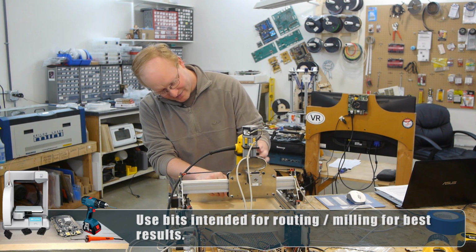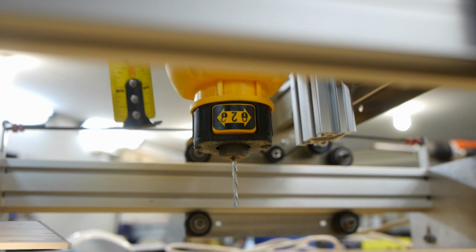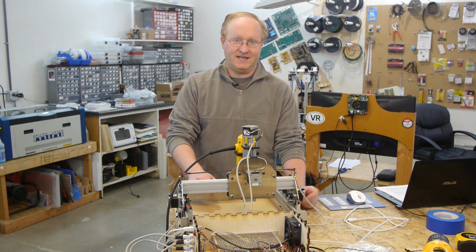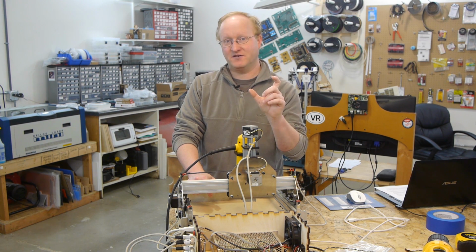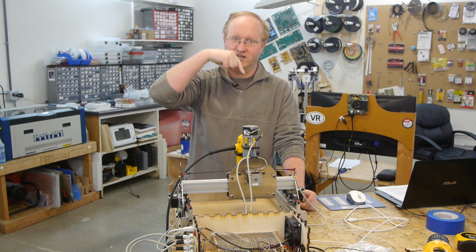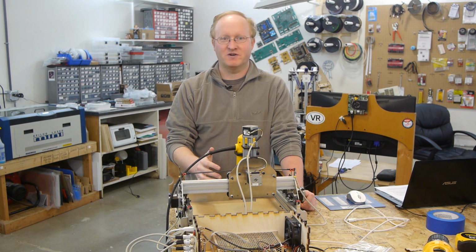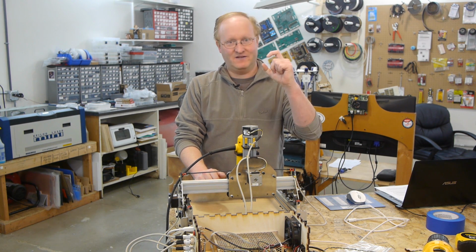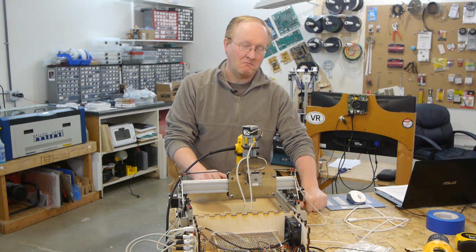You also need to think about how much cutting depth you're going to get. You're limited by the travel of the tool, and you're also limited by the length of the bit. In fact, the length of the bit is the biggest limitation. You can get bits that are an inch and a half long, fairly long bits, but you have to be concerned about breakage. The longer the bit is, the more it can wiggle, the more it can shatter, the more it will wobble at the end. So I typically like to use the shortest bit possible for the job. Most of my bits on my big CNC are only about half an inch long, and I just design according to that, and I very rarely break them.